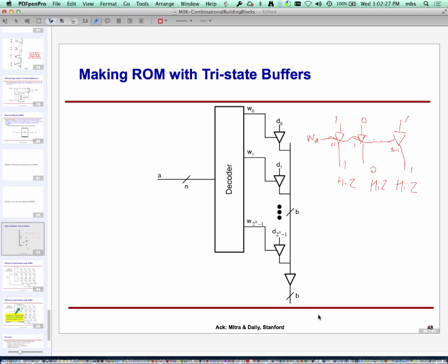So oftentimes what is done is you create a table. You pre-calculate values of that mathematical function, sine, let's say, and store them into a ROM, into some non-writable, constant area of your chip. And then whenever you need, like, sine of 90 degrees, you convert that into an address. You look up the address, and you have your value of sine. So ROMs are often used for this kind of purpose.